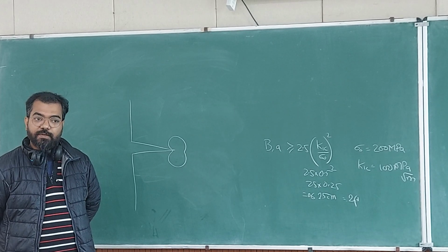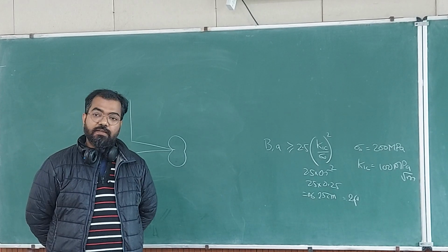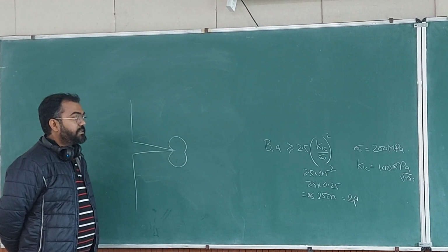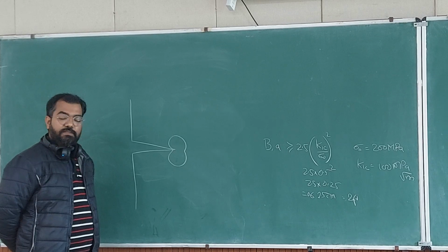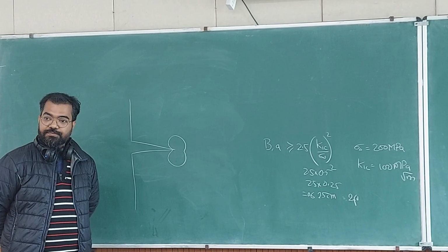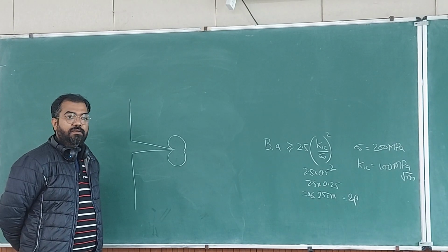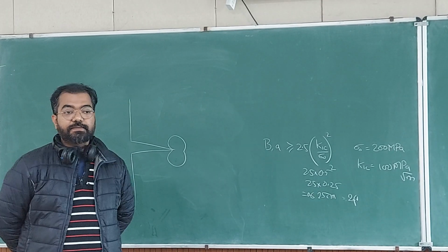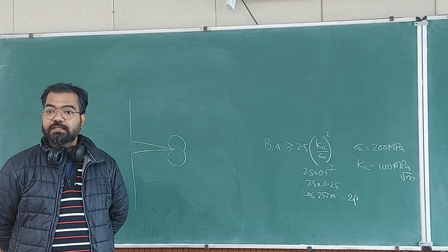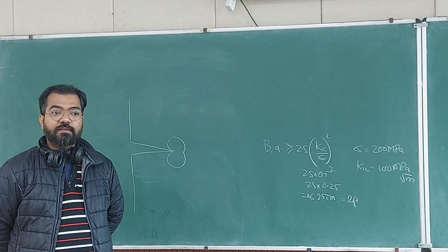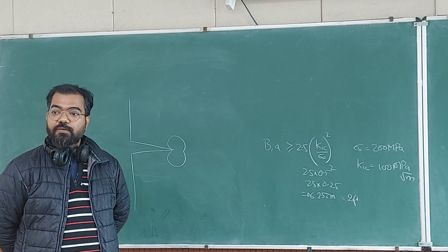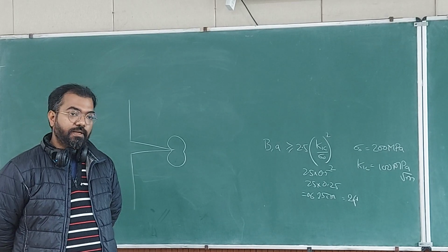The problem is coming because of the plastic zone. If you remember, this field started with Griffith. He tested on glass. Then Irwin was working with brittle steels, BCC alloys, which were breaking when the ship was just in port, so you need to revise your theory.